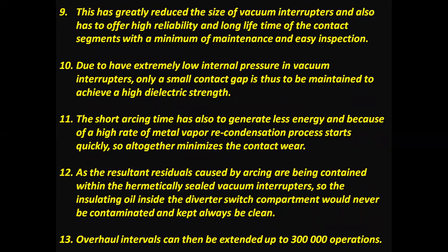Due to the extremely low internal pressure in vacuum interrupters, only a small contact gap needs to be maintained to achieve a high dielectric strength. The short arcing time also generates less energy, and because the metal vapor recondensation process starts quickly, it altogether minimizes the contact wear process.